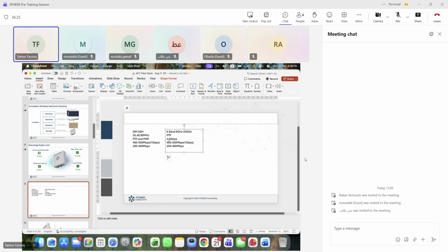Secondly, when you are talking about 2.5 gigabits, that means you will need a 2+0 kind of configuration, which means you will have to buy two radios and two different frequency licenses, and use them as XPIC on a multi-band antenna and then run it. So no point to multipoint at all, only point to point.